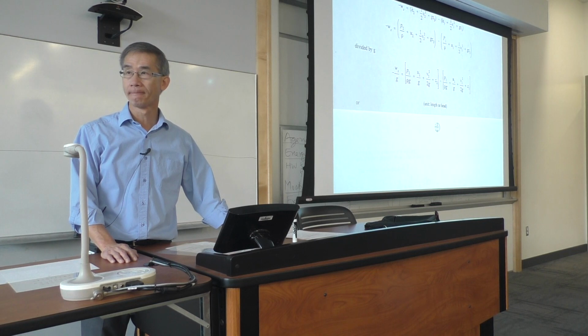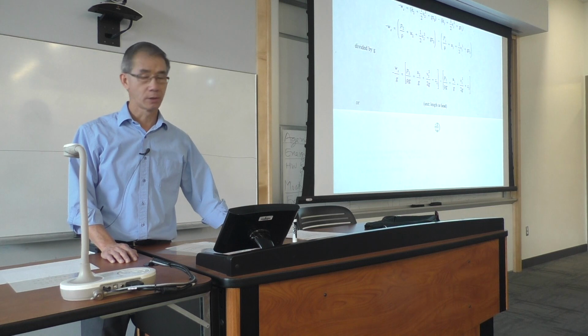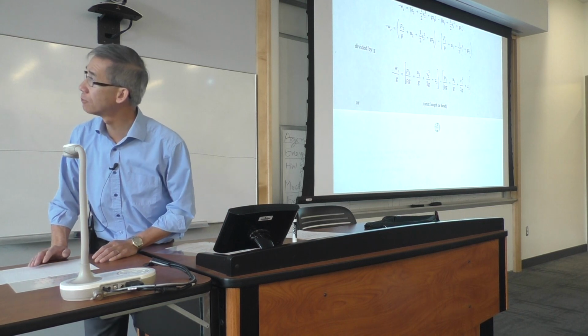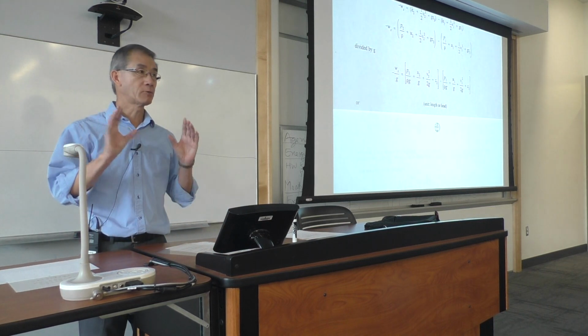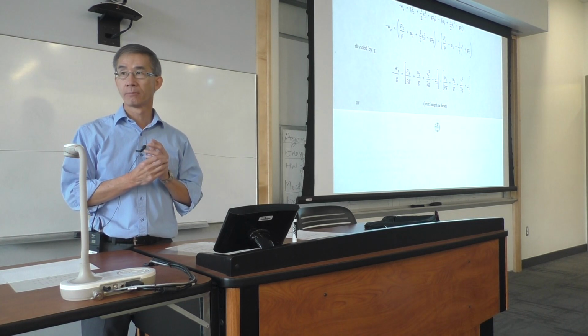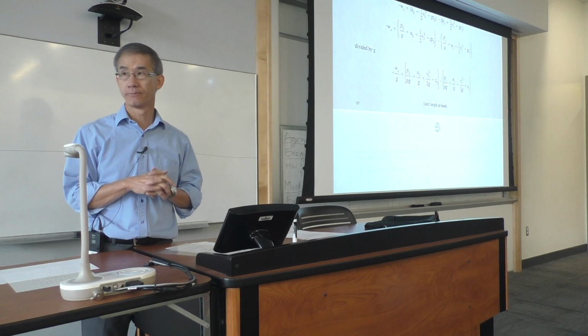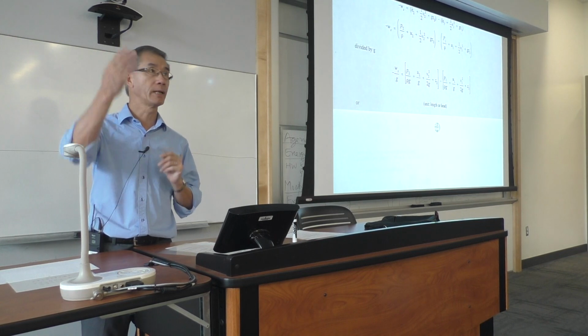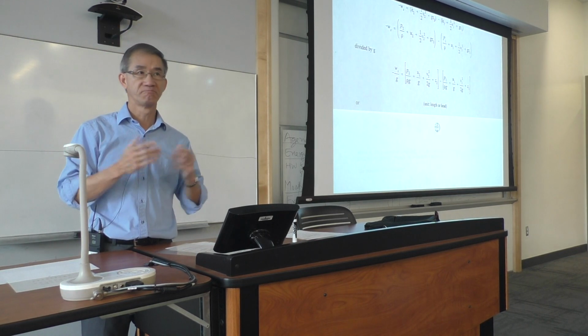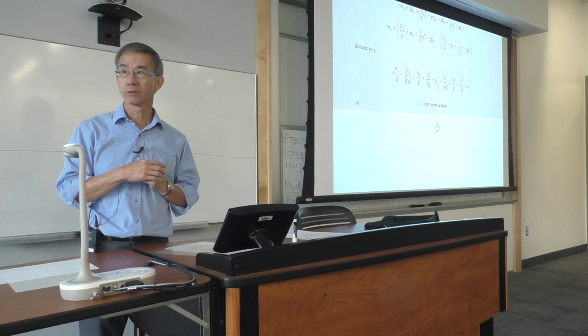Yes? Are you assuming no heat transfer to cancel out the U2 and U1? No, that has nothing to do with canceling U2 and U1. First of all, the heat transfer is totally unrelated. But for most fluid problems, heat transfer is really inconsequential. So we can always throw it out. In a pipe in the HVAC, heating a couple of degrees is inconsequential.